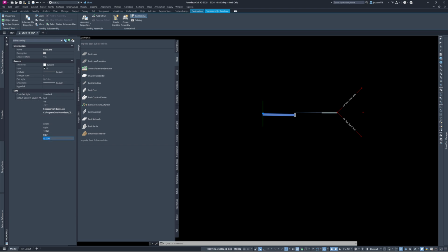And then the slope. This is set to default 2. I'm going to bump it up to 3 just to make sure. I know I have some flatter areas of roadway in this design, so I want to make sure that the water gets off the road into the curbs, so I make it a little steeper. Okay, so that's the curb, or that's the basic lane.